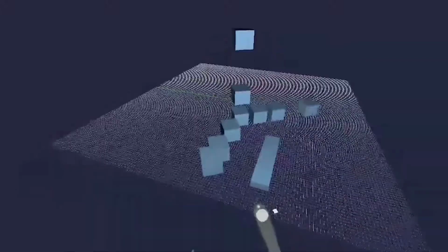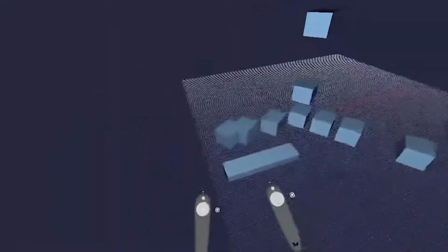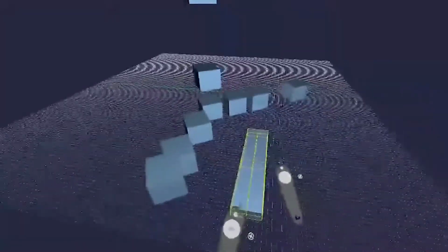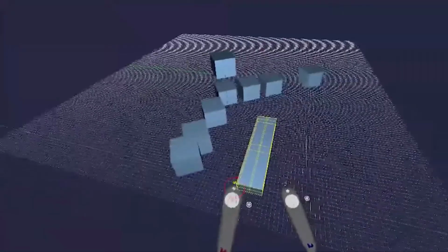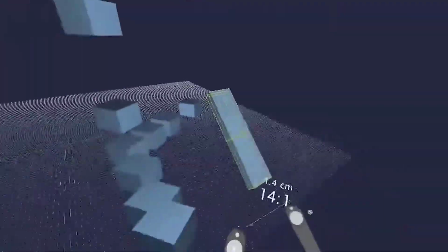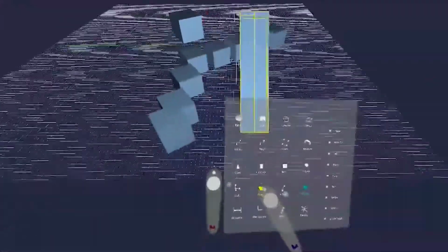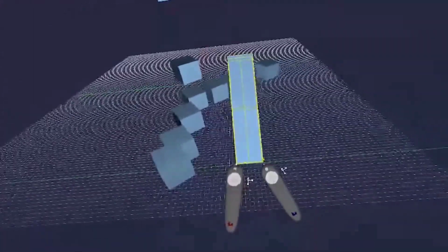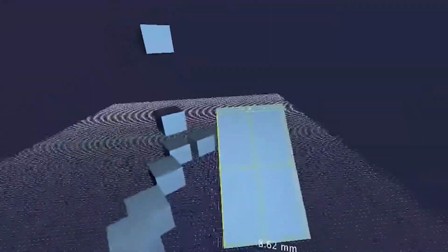Similar to other commands like rotate, for example, so we can go ahead and select this box. And using my left cursor, I select the base point, and my right cursor, I bring up the rotation, and notice that it's on the XY of the new grid. I can also scale in the same grid system from left to right, and there we are.